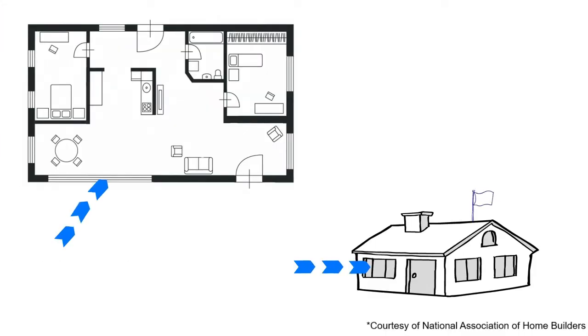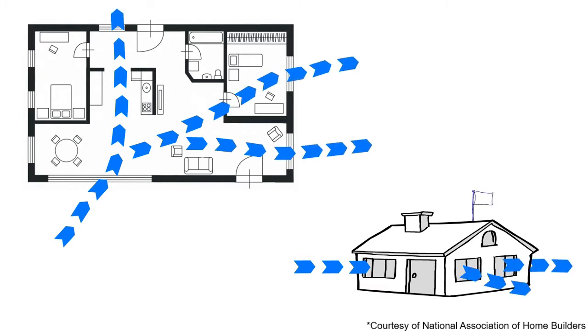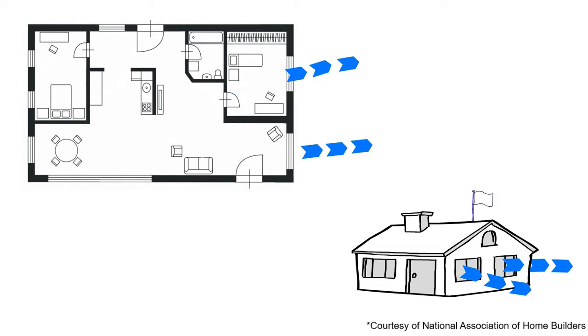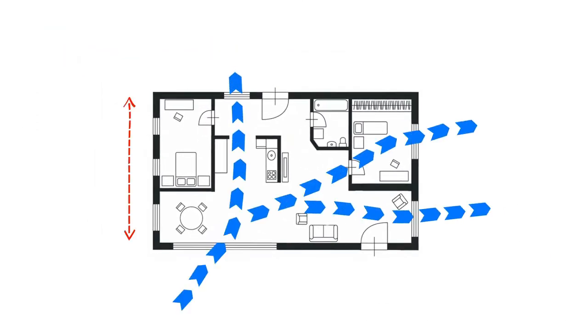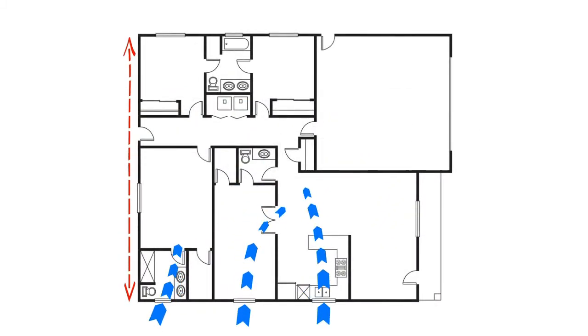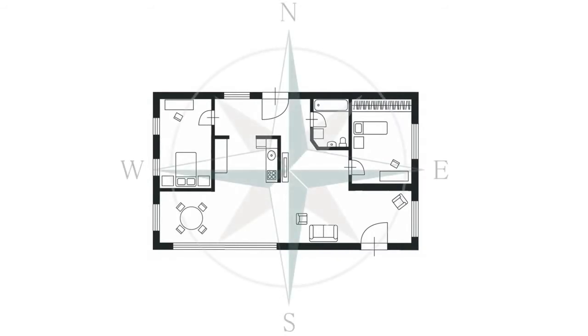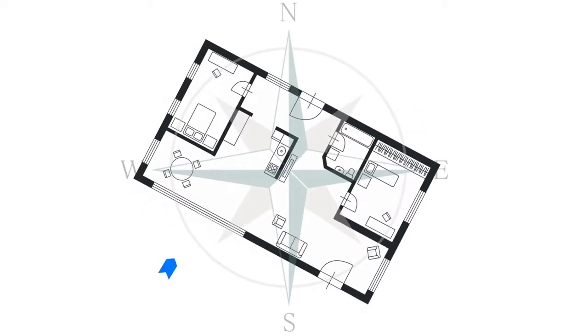Cross-ventilation is one of the most common forms of passive ventilation for a space, one that uses wind to bring the air through the building. It works by having wind enter through an opening and allowing the air to flow in and out through another opening. Some of the key factors for good and effective cross-ventilation are the size and orientation of the building. In general, narrow buildings tend to have better cross-ventilation. It is difficult to distribute fresh air to all portions of a very wide building using natural ventilation.